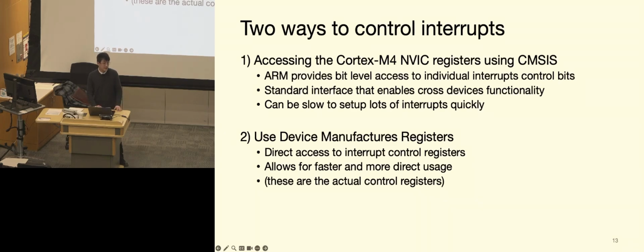The CMSIS, the top one, is a software framework developed by ARM to simplify the embedded software controls, or interacting with the interrupts. It provides what they call a hardware abstraction layer, HAL. Not sure how many of you are familiar with that term. So basically, it's an interface between the application program and the hardware levels down there. So it's an additional layer for you to make it easier as programmers to access.